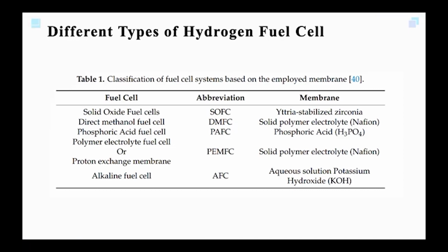The polymer exchange membrane fuel cell had already been introduced to some automakers such as Toyota, Hyundai, and General Motors for making the hybrid electric vehicle. PEMFC HEV seems to be a reliable dynamic system for the future, but its durability is much lower than other dynamic systems at present. The main cause of low durability is the component called membrane electrode assembly, with a short lifetime of about 1,000 hours, and it cannot reach the basic requirement for cells, which is around 5,000 hours.